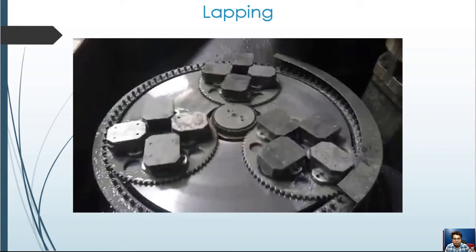The following materials can be processed by lapping: metals, ceramics, glasses, natural materials like marble, granite, basalt, any kind of gems, plastics, materials used in semiconductor technology, as well as carbon, graphite, and even diamond. Geometrically complex components with little form stability can be embedded in a supporting mass, thus expanding the area of application of the lapping method. Now we shall see a video of the lapping process.